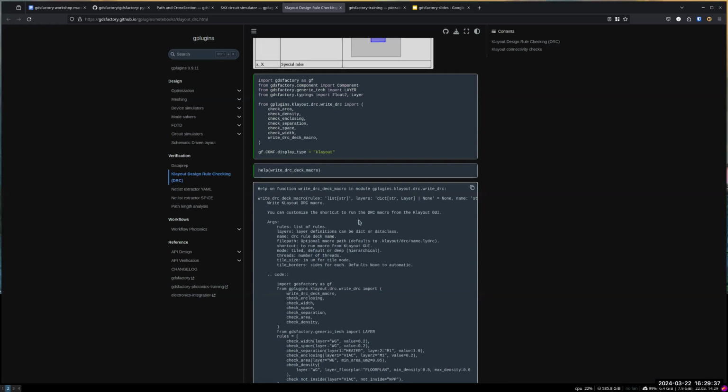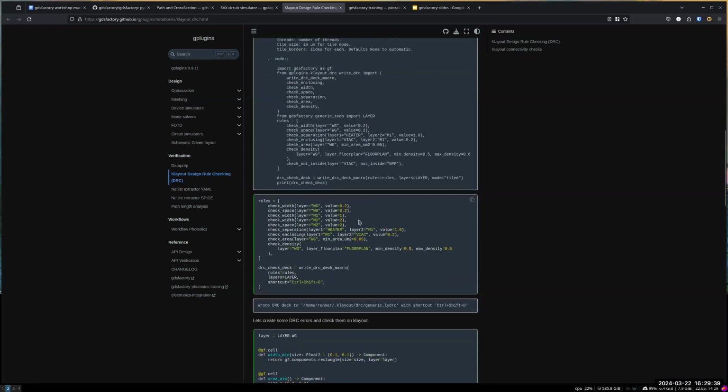Most of the foundries are giving these rules in a different proprietary tool called Calibre. So yeah, we can help you with that. If you want to get a Calibre rule deck, you have to either get one from the foundry or write one yourself. But we can help you write the DRC deck as I did before, but it will write them in KLayout. So they will only run in KLayout. Does it answer your question? I don't know.